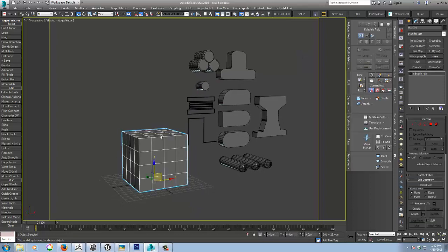So I'll select our cube here, and I actually did a video like this, I don't know, a while back. It was kind of just more of a test. I wanted to see if I could mimic the Boolean operations in ZBrush using subdivided Boolean over here in Max, and also doing it non-destructively in the stack. So this time I've just decided to return to the same subject, but instead of using subdivisions, I'm just going to use the Chamfer modifier, or quad chamfer as it was known until it was plugged into Max.